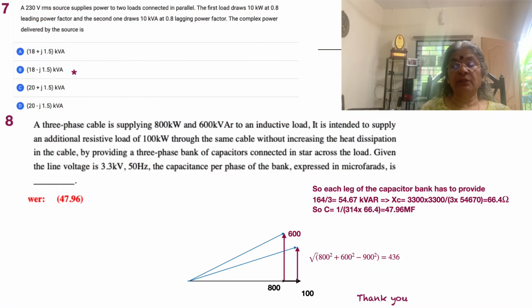So if you deduct from 1000 kVA the 900, vectorially, that is 1000 square minus 900 square, then take the square root, you will see that the machine, whatever the power, still takes 436 kVAr.